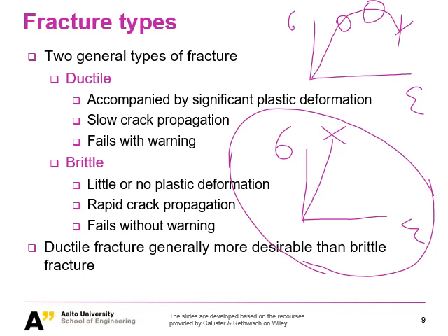And thirdly, which is the most detrimental part of brittle fracture, it happens without warning. So the stress increases, the load increases, and at a certain point that you don't know, the fracture just happens without any warning. You cannot really take a precaution about it, plus there is very fast crack propagation. That makes brittle fracture the most detrimental fracture in our engineering materials and structures.